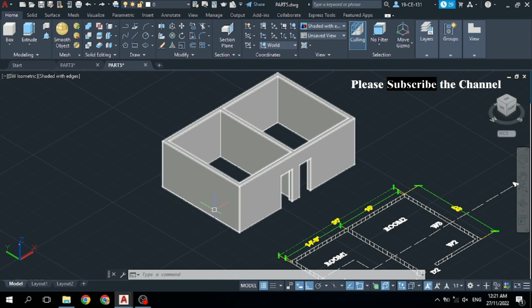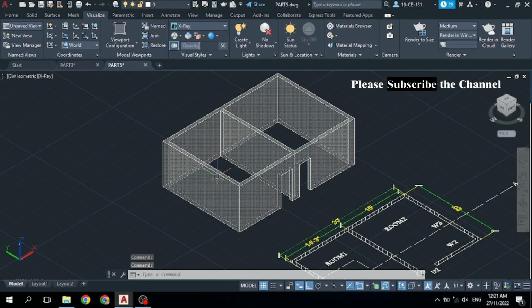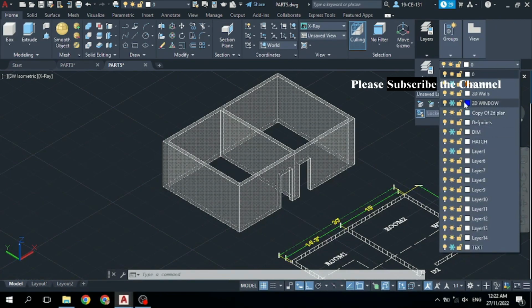So for that I would be in X-ray mode. Come to Visualize, click on this Visual Style, come here and select this X-ray. Now you can see these hidden lines and areas are visible. After that come to Layers and make this window layer visible. Now you can see this window layer is invisible, so I would like to click to make it visible.